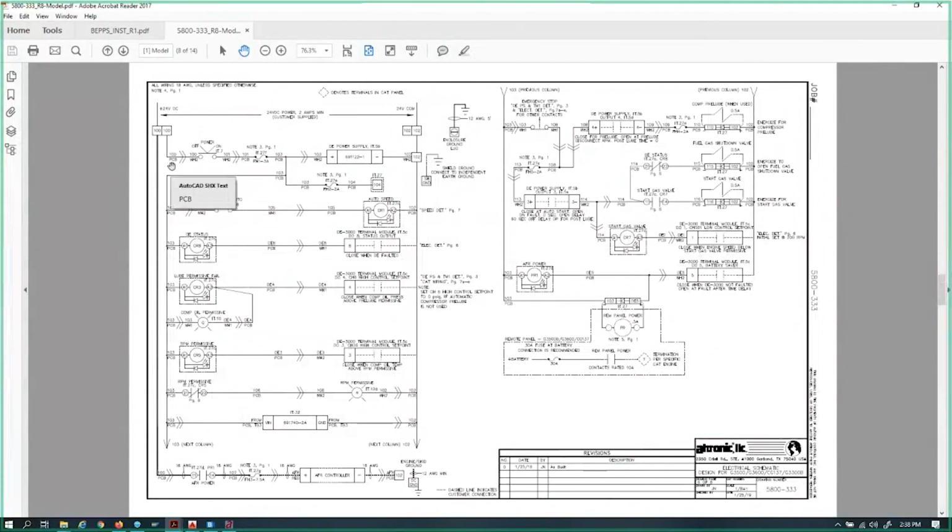We come from block 100, which is identified by a PCB, through a Chevron, which indicates it's a wiring harness connection, 1 or 2. We tell you it's still wire 100, which is true. It's not changed. Still wire 100, but now it's part of wiring harness number 2. Goes into a switch, wire 101, wiring harness number 2, enters back in through the connector onto the PCB, goes through a fuse, still on the PCB, but now it's wire 103.